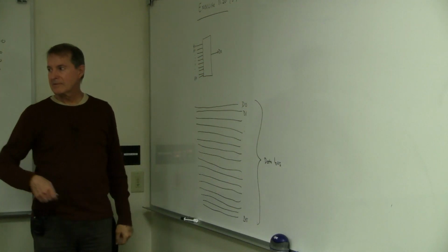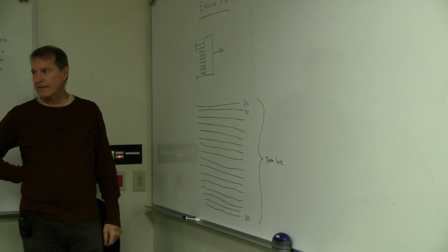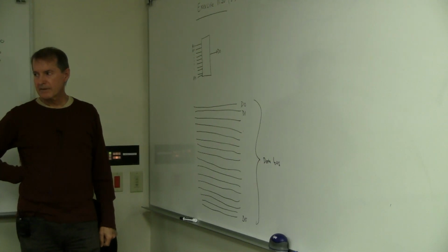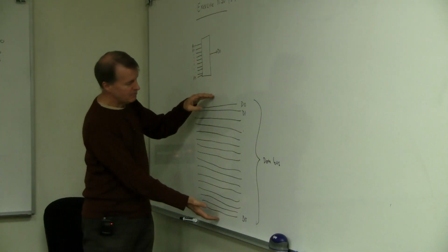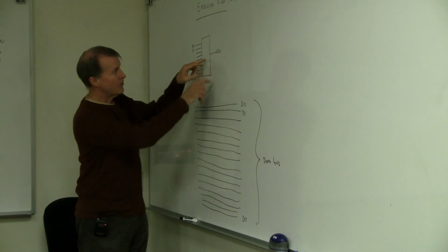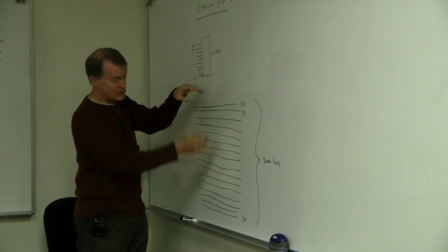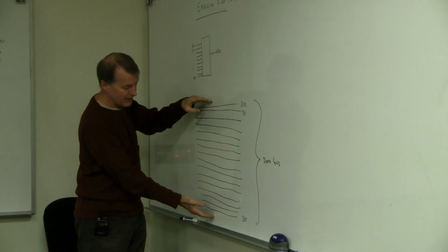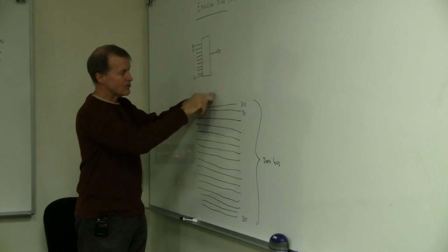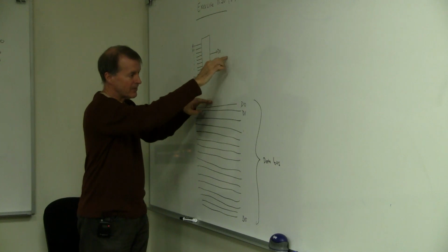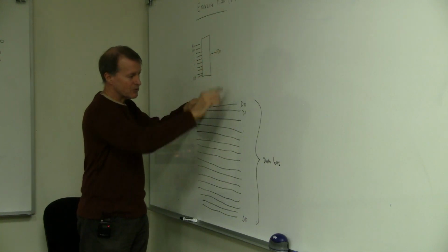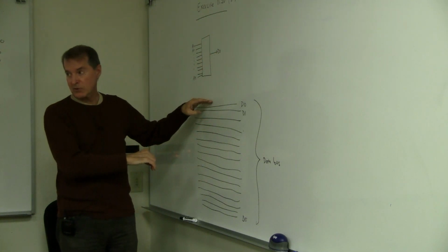But I'm confused: if the chip is 1024 bits, and then the data bus is 2 bytes? Yes, it's 16 bits. So in order to fully populate the data bus, the D0 of each chip goes to the next line on the bus.